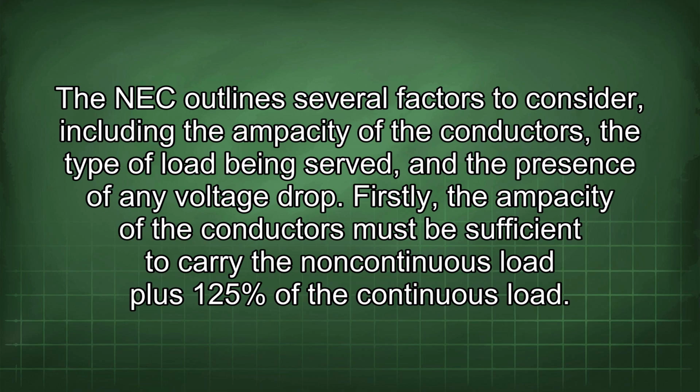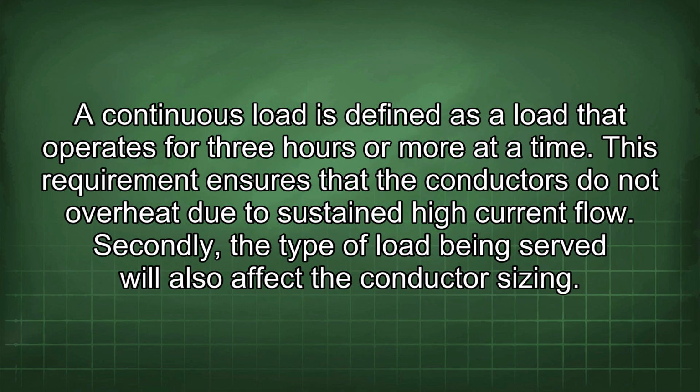Firstly, the ampacity of the conductors must be sufficient to carry the non-continuous load plus 125% of the continuous load. A continuous load is defined as a load that operates for 3 hours or more at a time. This requirement ensures that the conductors do not overheat due to sustained high current flow.